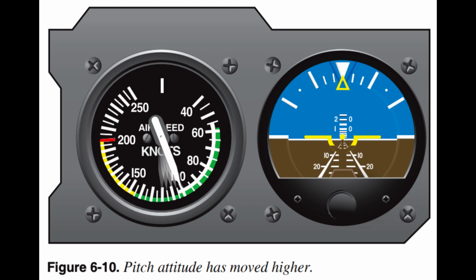Common errors in pitch attitude control are: 1. Over-controlling, 2. Improperly using power, and 3. Failing to adequately cross-check the pitch attitude instruments and take corrective action when pitch attitude change is needed. Bank control.